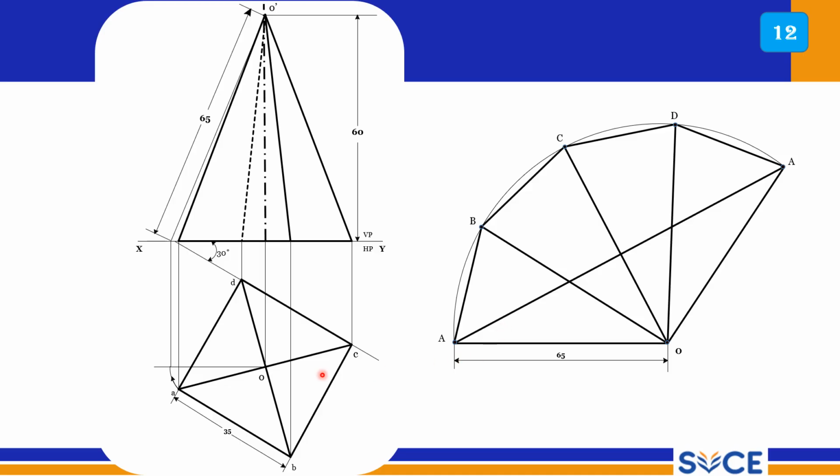And now students, the shortest distance between two points is obviously a straight line, right. So from this corner to this corner you draw a straight line. It is nothing but the string. Now string is wound around the solid, right. So now in this order you have to connect it. So A to A should be connected with a straight line, and now you can mark the points on each edge, right. Those points can be marked here.